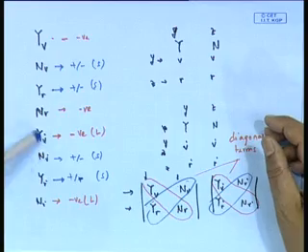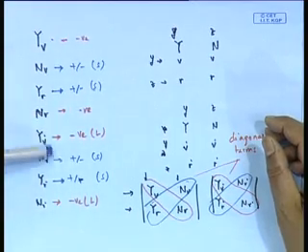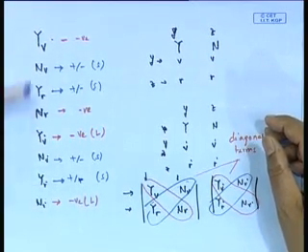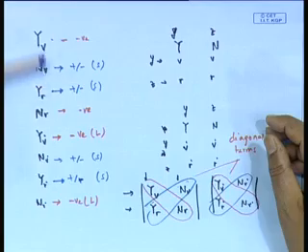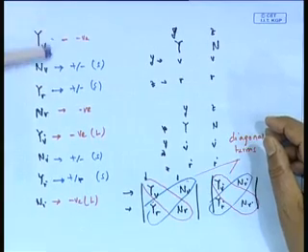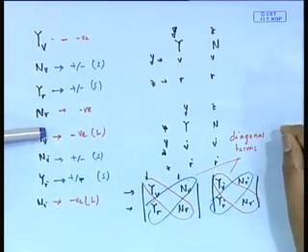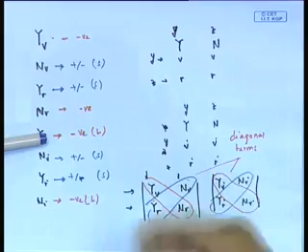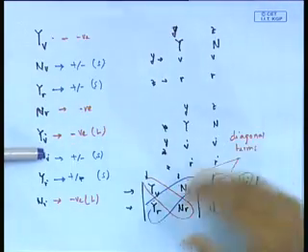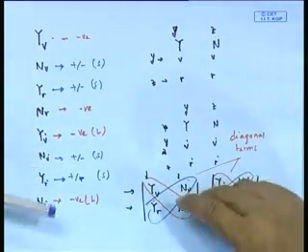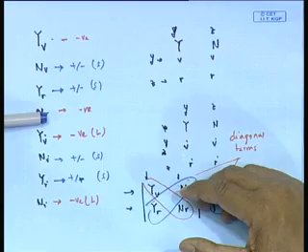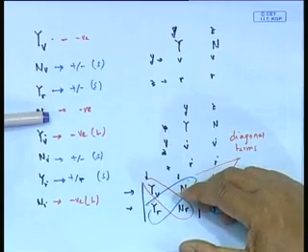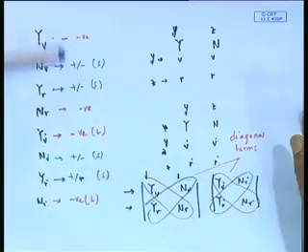This is a very important and interesting point, of which, as I told you, these terms are added mass terms, these are damping terms. Added mass terms are inertia forces, these are forces because of velocity. We do not yet know necessarily, or rather I can say that understanding of these forces is more known. However, we will find out in the next class that the importance of this is much more as far as maneuvering is concerned. In fact, maneuvering characteristics, stability characteristics will be decided by basically these quantities.